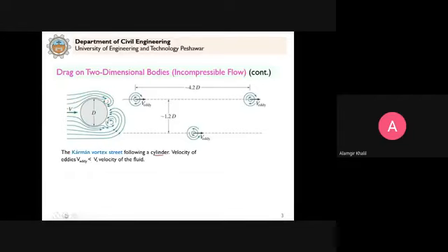Now, when the fluid flows past this cylinder of diameter d, when the Reynolds number increases, meaning this velocity increases, these vortices will form. There is a backflow; you can see the liquid flows in the backward direction, swirling in a rotation, and similarly on the other side also.